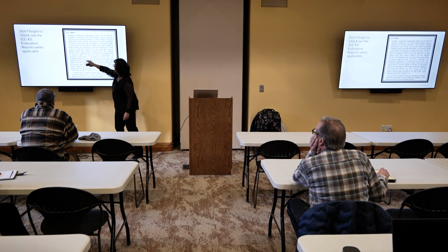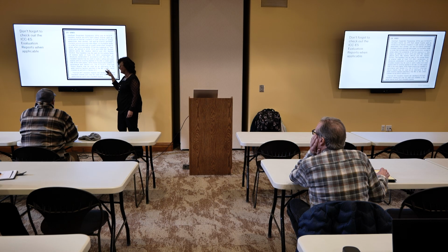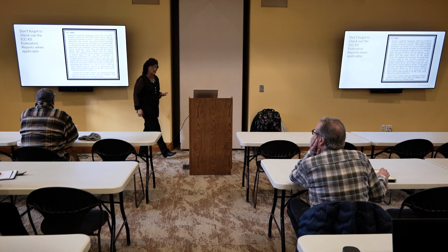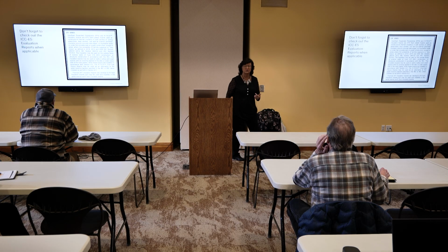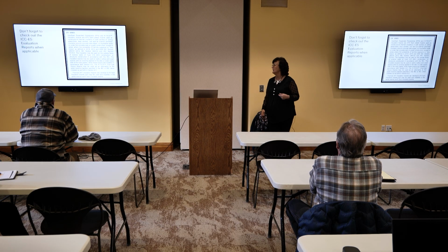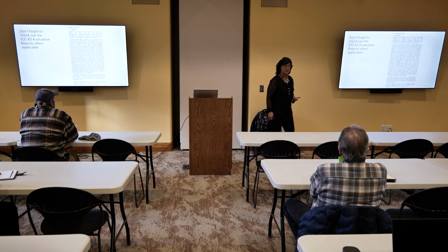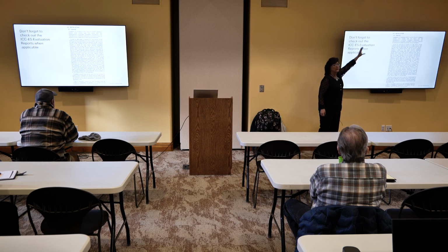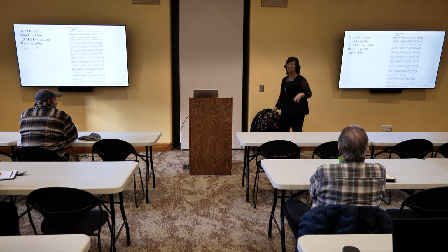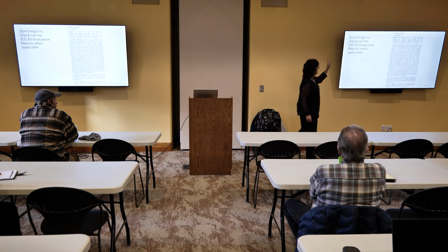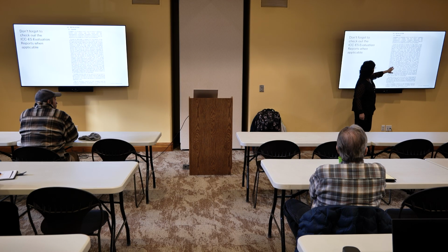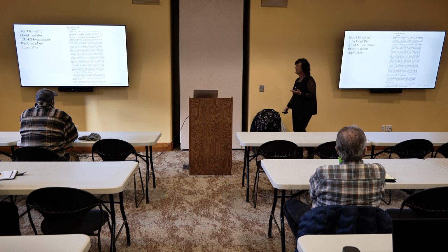Then it goes on here. If I put it on a wall in an attic or a crawl space and no covering is applied, then it has to meet these requirements. It'll always tell you: do I have to cover it up? How do I have to screw it on? Where is it allowed to be used? It gives you all the uses, and then it'll go through and say, okay, here's how it has to be installed. If you want it to meet thermal, you install it this way. If you want it to meet water resistive barrier, it has to be done this way. And it goes through all of it: what thickness it has to be, how far it can be penetrated, and all kinds of information on how it has to be installed.